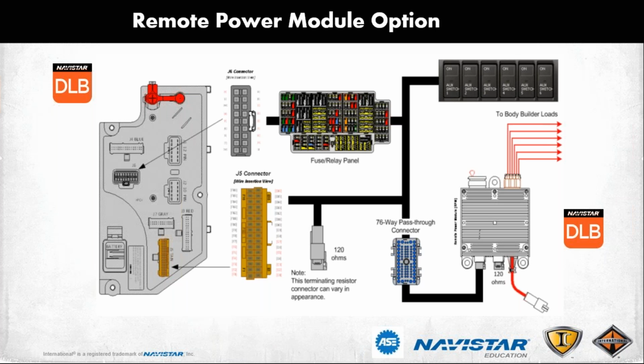Air solenoid options. These trucks can have a capability of 16 air solenoids, which will give us 4 manifolds or brackets. The solenoids come in 3 varieties. The color of the ring identifies its purpose. A yellow color ring is a normally closed solenoid. When it's de-energized, there's no air coming out. The yellow ring identifies it as air horn only, and it'll flow approximately 6 cubic feet per minute of air out. It's all 1/4 inch push to connect brake line going into these. The exhaust is out the bottom.